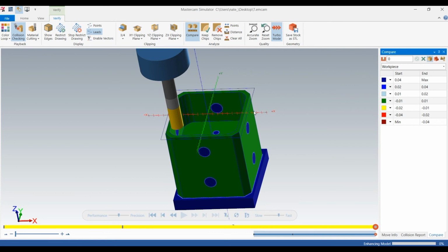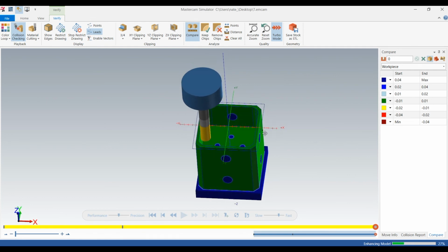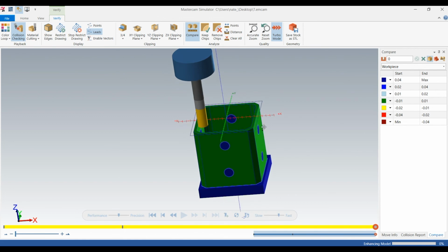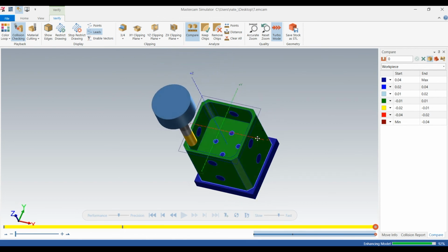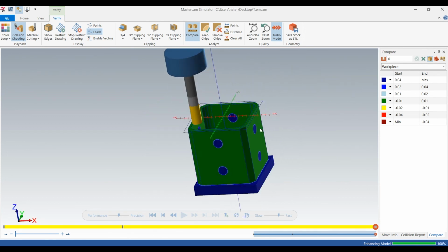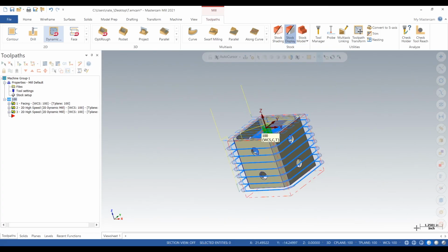And it's kind of just that simple. It's not a real tough toolpath to learn. You just have to make sure you select the right geometry and you're either on the inside or outside. And then just control your step overs or depth cuts. And select the right tools for the job and you'll be good to go. I always verify everything and then use a compare just to make sure we're not cutting anything extra or not cutting enough. So the next video will be all about putting in those side holes, 3+2.